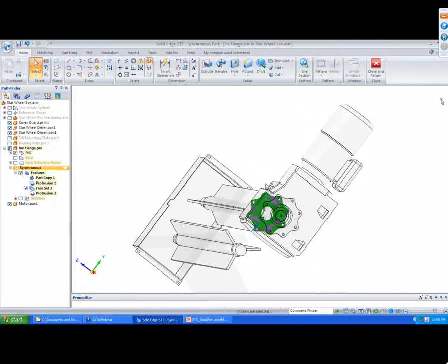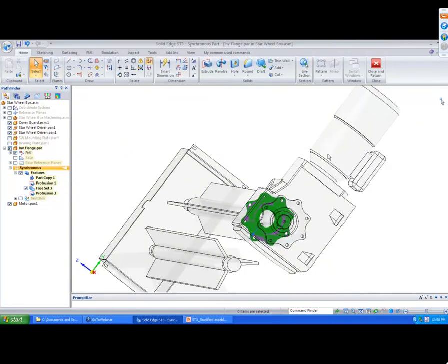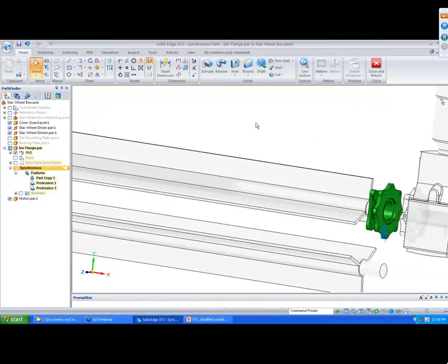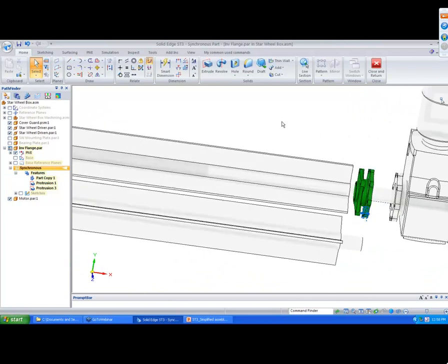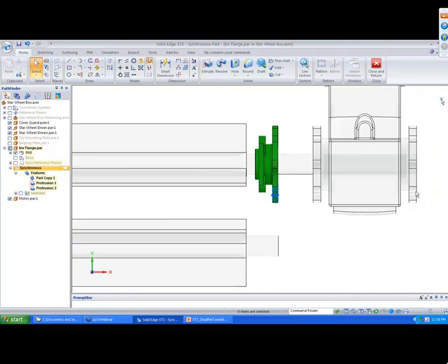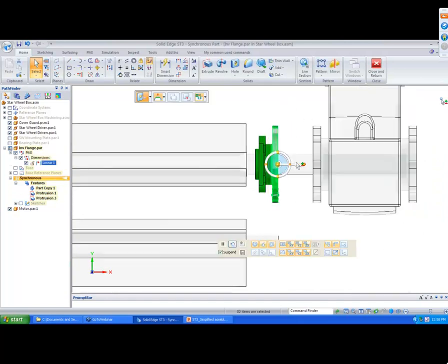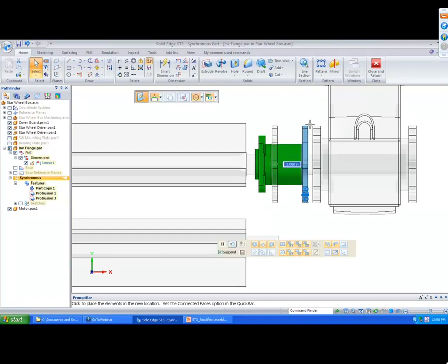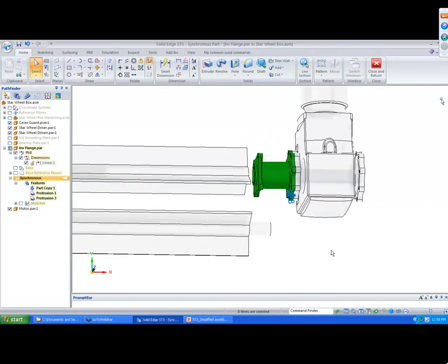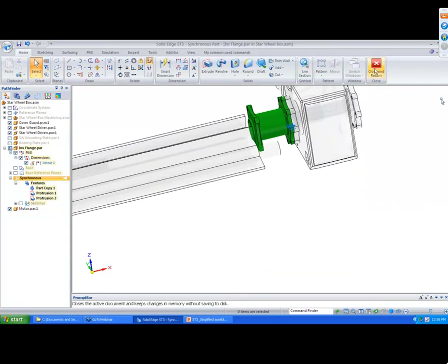Alright, I don't need that copied surface, so I would delete the surface which I just copied. I can just right click this surface and delete it. So that will take care of that. I also want to extend this flange, so I'll just go to the top view, and now I can just window select the flange, and with the help of my steering wheel I can just select the endpoint here, and that will take care of the mating.